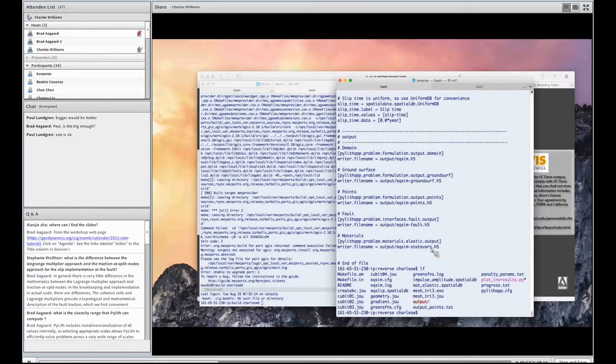So you just do that by running pylith eqsim.config. Now, I don't know if we went over this. Usually it's handy to also save a log file when you run a simulation, just in case you run into problems. So that's what I'm doing right here.